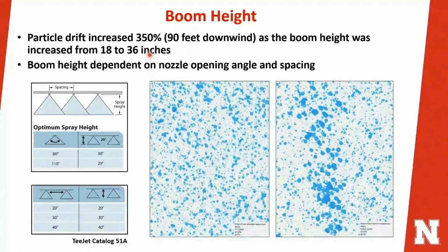But this unfortunately doesn't mean that we can go out there and just drop our boom height, right? Because if you take a look in the nozzle manufacturer guides, we will see that there is a direct relationship between the nozzle spacing and the spray height from the target that we are working with. And this is also influenced by the nozzle angle, if you're working with a 110-degree nozzle or with an 80-degree nozzle. So unfortunately, we need to respect those rules there in the nozzle manufacturer guides.